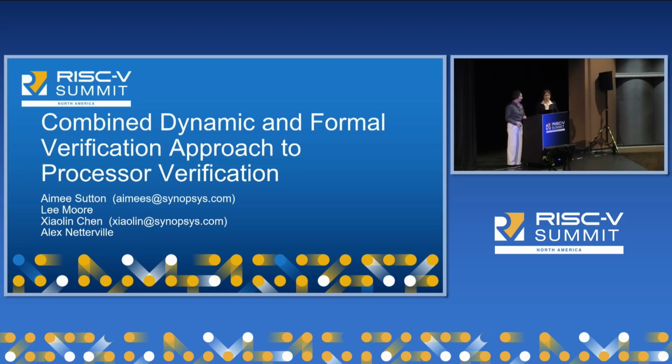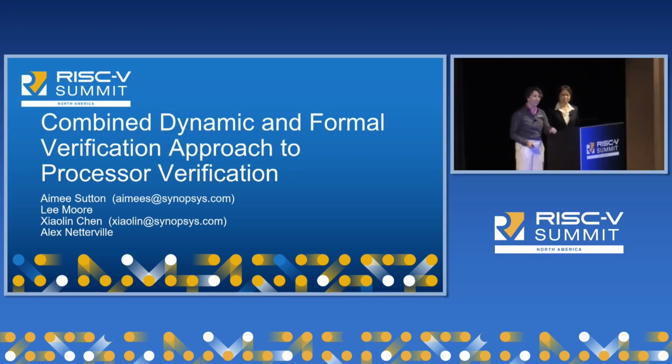I'm here with my colleague, Xiaolin Chen, and we're here to talk to you about combining dynamic and formal verification techniques to improve the overall quality of your RISC-V processor IP. So I represent the dynamic side of this partnership. And when we talk about dynamic methods, we're referring to the process of applying stimulus to the design under test and then observing its response in either simulation, emulation, or FPGA prototyping environments.